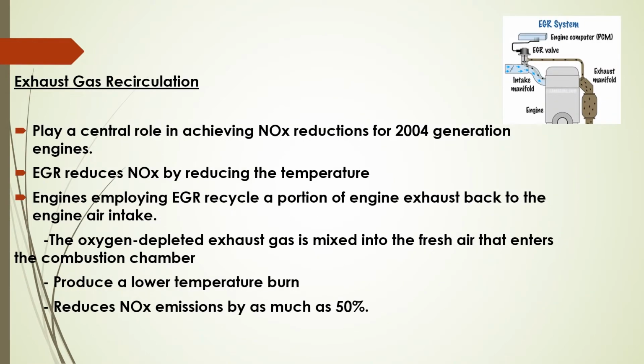Not only that, exhaust gas recirculation is one of the most advanced technologies that can contribute in improving the performance of the diesel engines. Exhaust gas recirculation, known as EGR, will play a central role in achieving nitrogen oxide reductions for 2004 generation engines. EGR reduces nitrogen oxides by reducing the temperatures at which fuel burns in the combustion chamber.